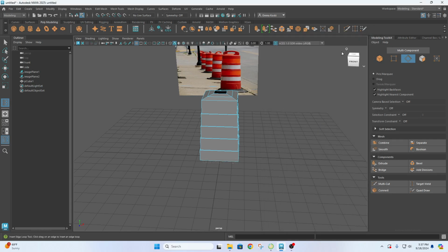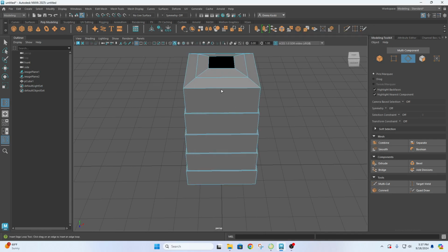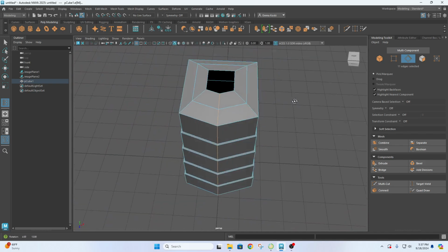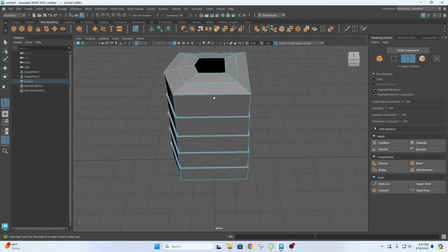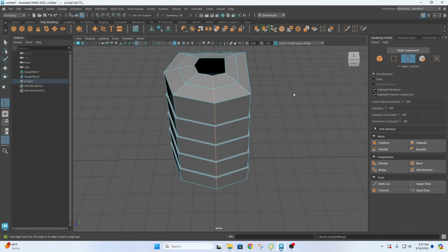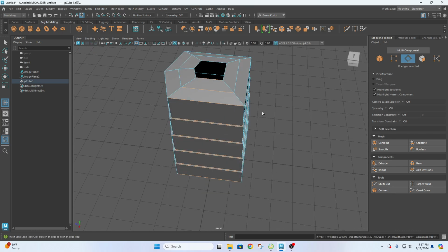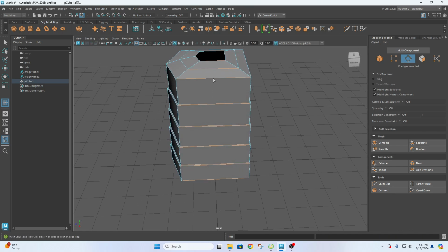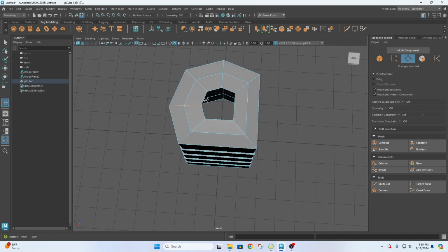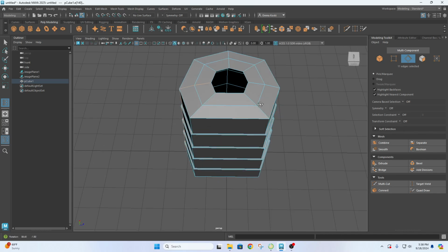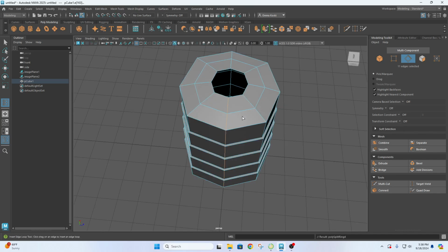It is. Awesome. Now we're going to come here and insert with edge flow, and it pops out our object. If you pan around, you can see it popped out the shape. That's awesome because we have Insert with Edge Flow selected, so we want it to do that. Now I'm going to go around and try to select about halfway in between each side. If you're not happy with where you put it, you can hit Control Z to undo it. So I'm going to go through getting about halfway.